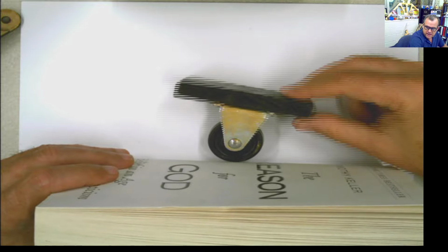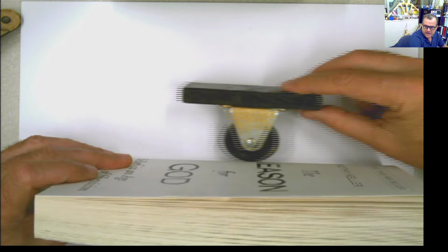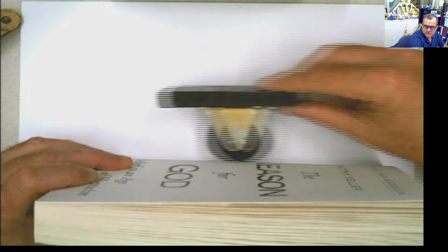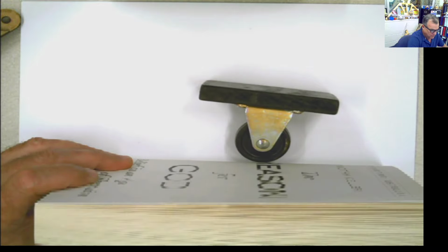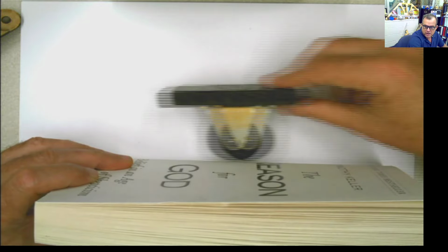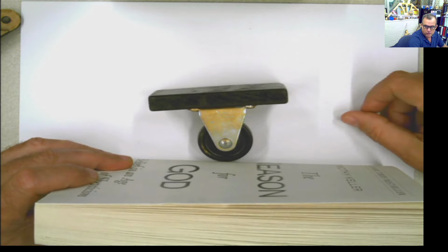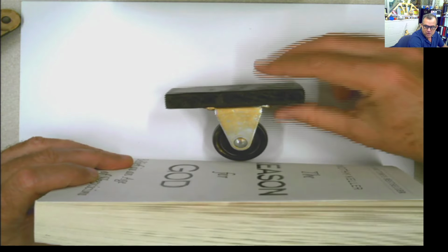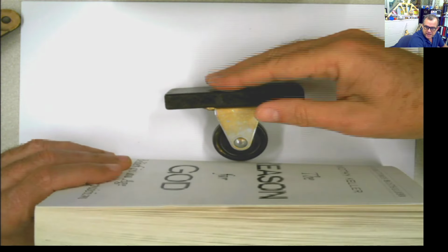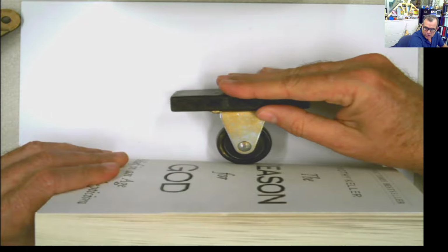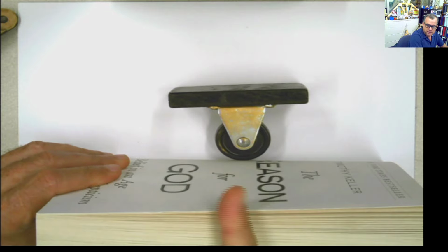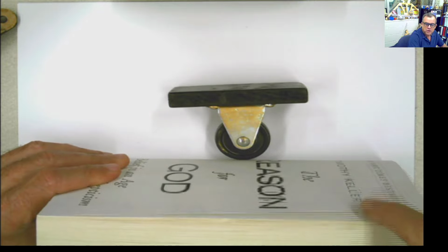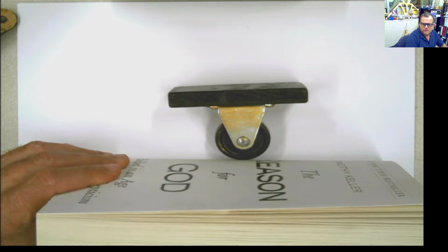So look at this again. These can rotate, and at the same time, these can slide, meaning there is not a moment reaction in this support, and there is not, in this particular case, a horizontal force, because it can translate. However, if I push it down like that, it's not going to go down. That means that there is a force reaction here, perpendicular to this part. Usually students say, oh, there is a force that is vertical.